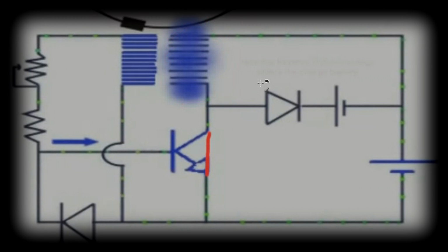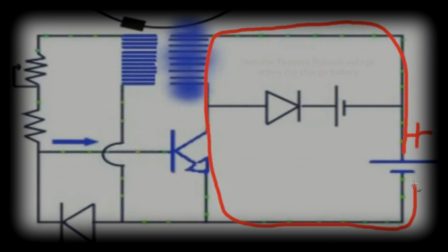And it's charging from battery potential plus right here, source battery. It's charging through here because the switch closed. So that means you have plus up here on this coil and minus down here in the charge cycle.